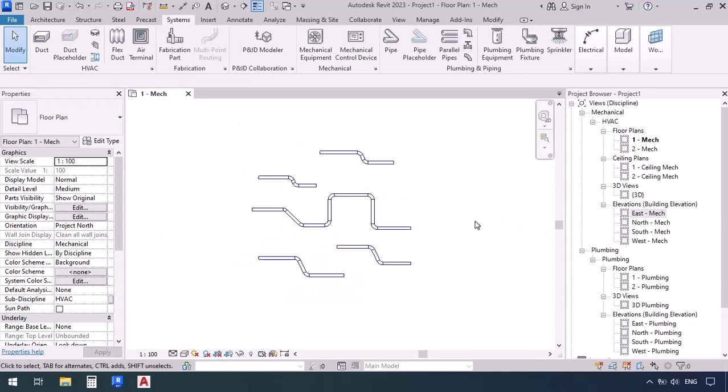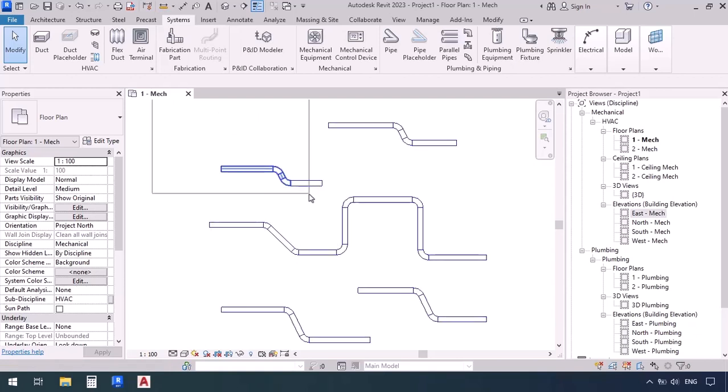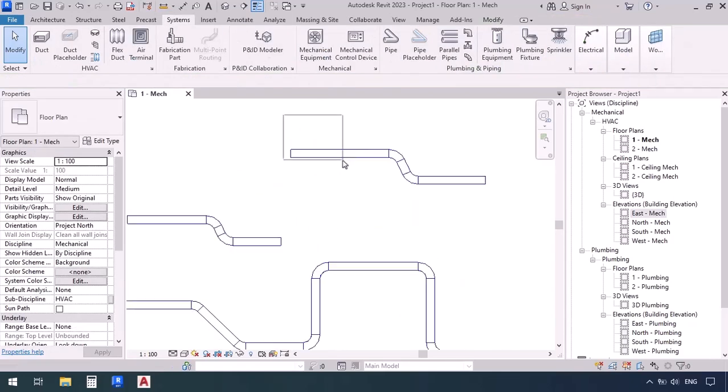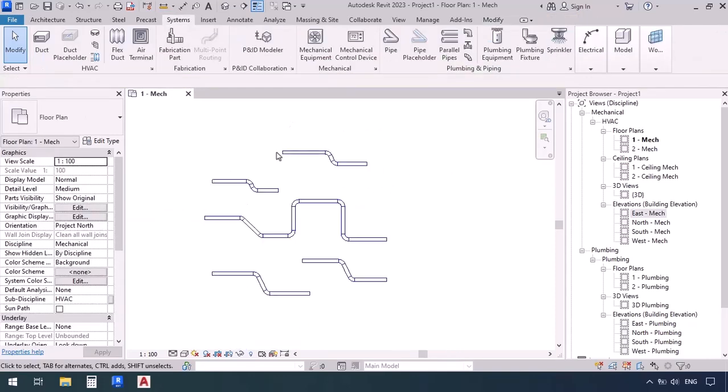Now I want to delete all of these ducts that I just drew so that we can talk about some other things. We can select the drawn items by clicking and dragging. If we click on the left side and then drag our mouse, each item that would go completely under that box would be selected. But if only a small part of it is included in that box, all of it wouldn't be selected. We have to hold a complete item.